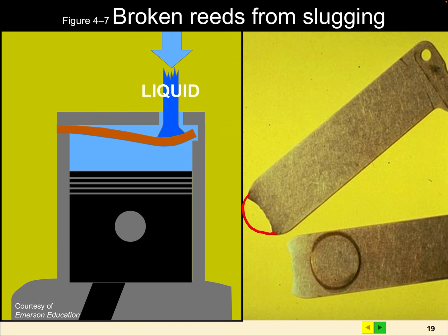So that section, literally probably from here, is broken and snapped off. In this picture, we can actually see the chattering of the valve, and you can see that little ridge all the way around there, and that's kind of an indicator that the valve suffered from tapping or excessive pressure on it. So those are a couple of examples, but that's really a very dangerous thing.